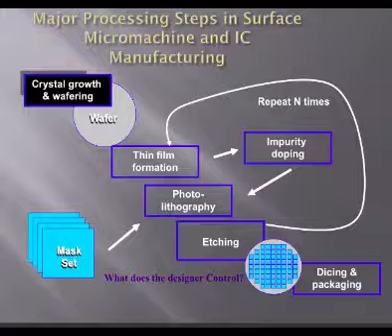So we did a lot of that at TI when I was there. You know, I had to know what that offset was. Okay? And it was really hard sometimes to explain that to the designers. You know, because let's say they draw something that's 1 micron, and then they put a 1 micron space, and then they draw something that's 1 micron, right? Because the minimum space is a micron, and the minimum width is a micron. But if I have to add 2/10, because I'm going to lose 2/10 in the process, now my space is 8/10 of a micron. If I have two lines too close together, they won't image right. They'll be fused.